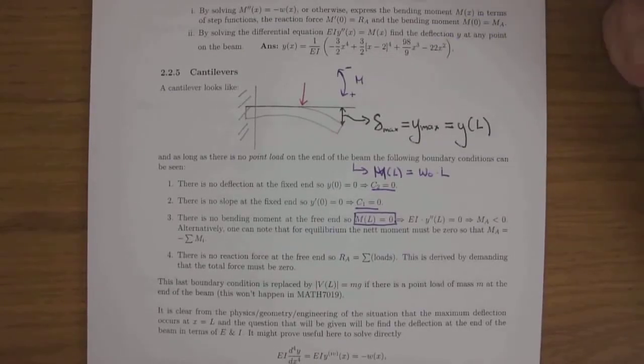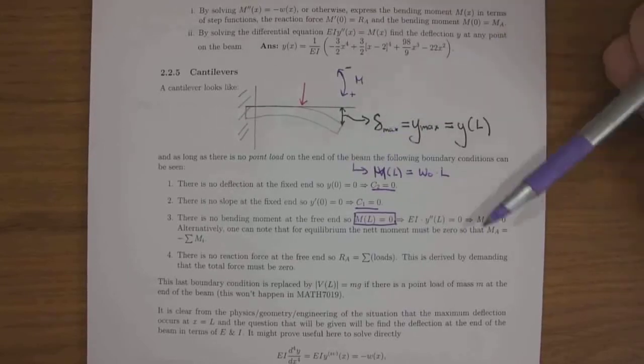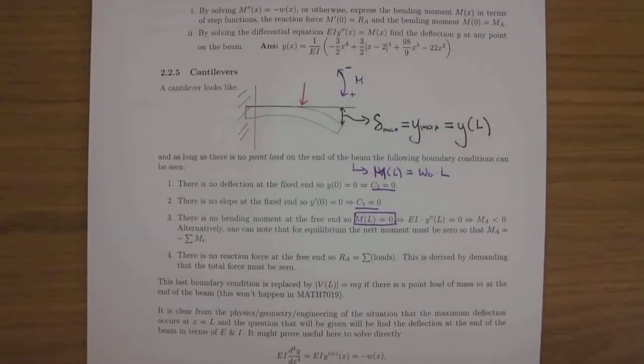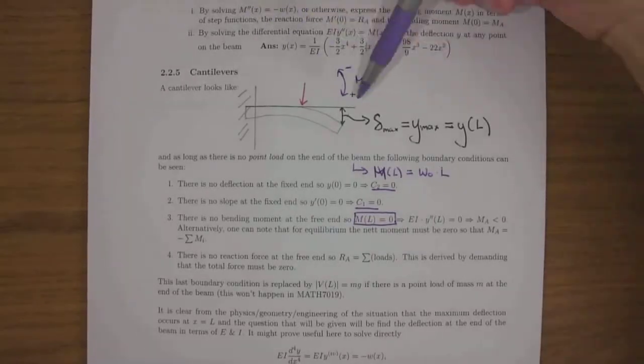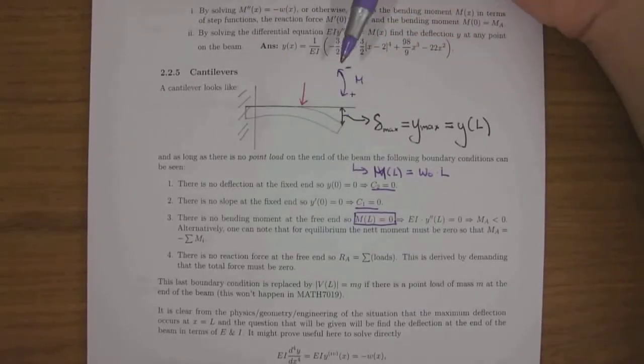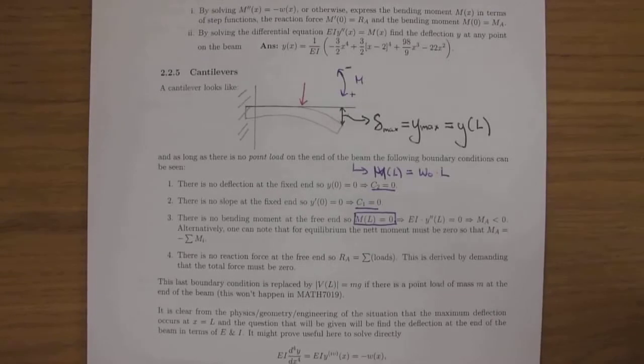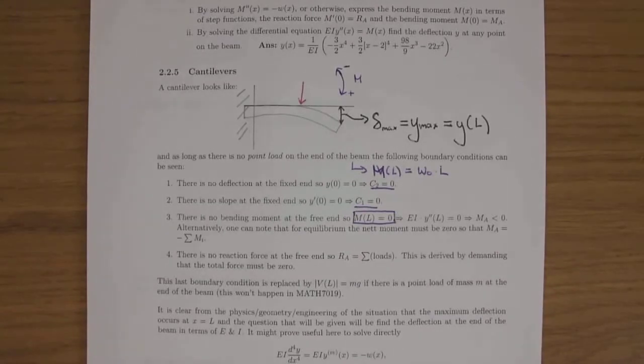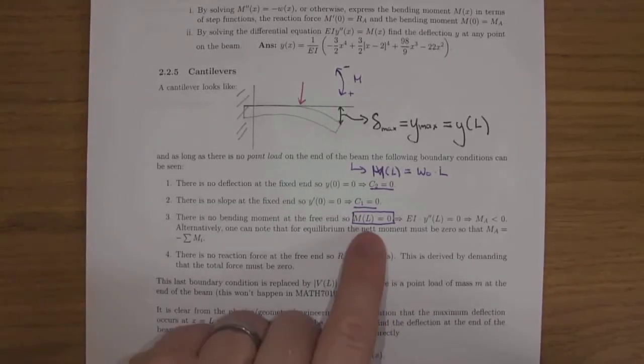The other thing you can do for equilibrium, because these are all equilibrium equations, nothing is moving, the bending moment at A must be minus the sum of the moments if you know how to calculate the moments due to individual loads, but that's not always going to do you, because in particular I think the moment due to a uniformly varying load is a little bit different, so that's not really going to be an approach that you take. Look, this is what you're going to do.